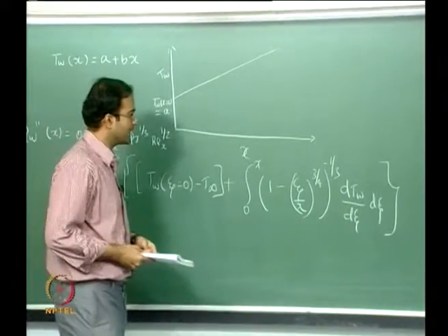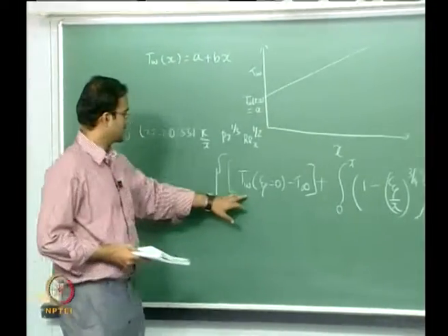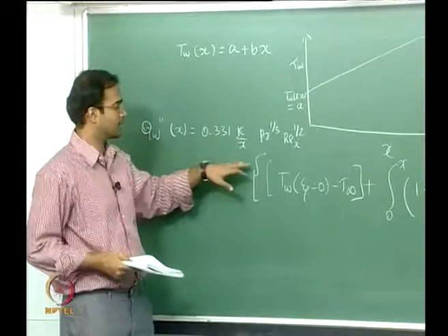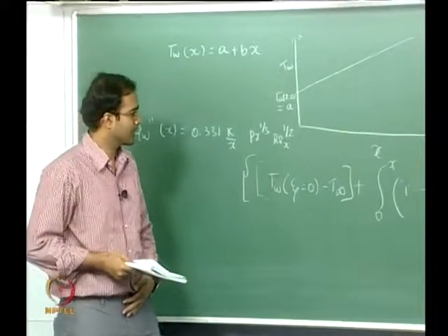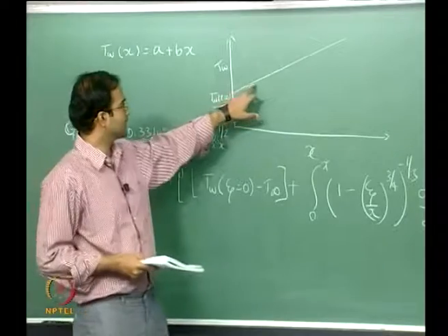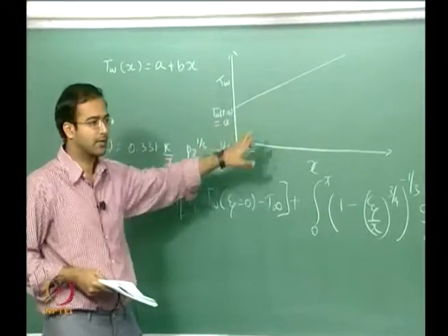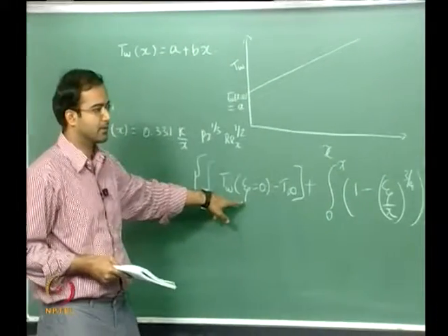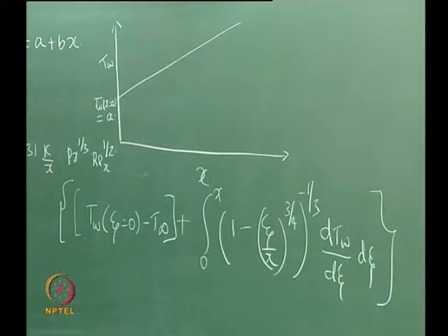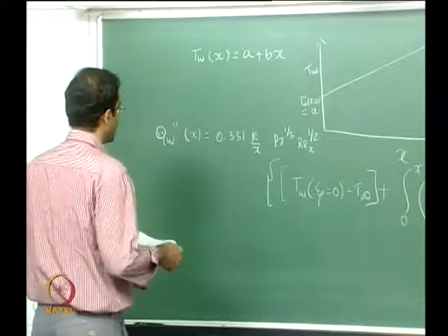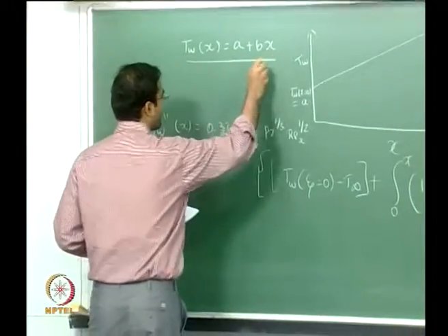So this is our expression. Now for the limiting case where you don't have any slope, the slope is 0, so this is T wall minus T infinity, and this becomes equal to your flat plate with a uniform temperature expression. Okay. So of course if you have continuous variation but also intermediate temperature jumps, there you have to introduce an additional delta T into h for those temperature jumps in between. Okay. So apart from that, this is the expression. Now we will substitute for the given temperature profile whatever we require.